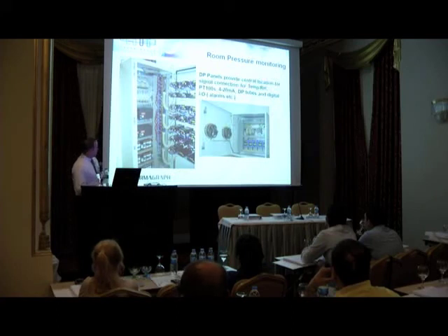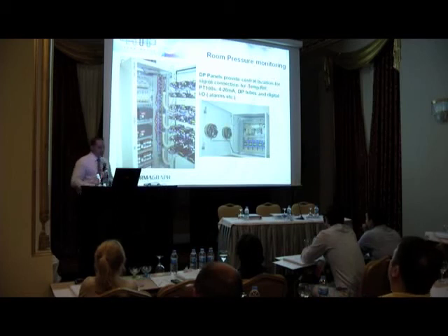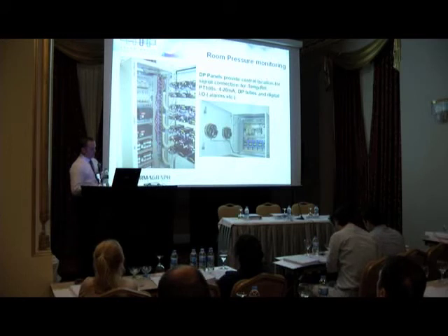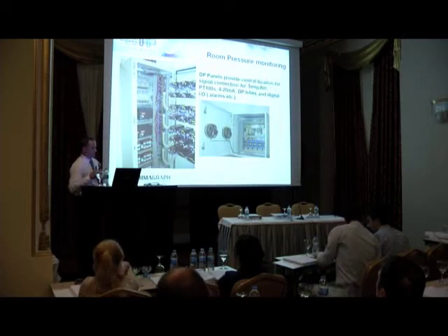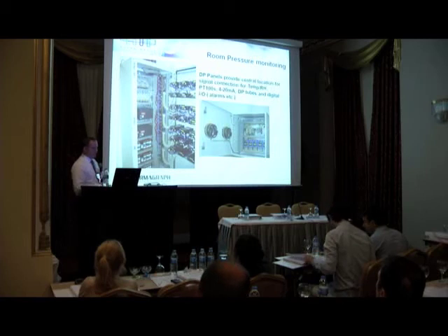We've also mentioned we can do a lot of pressure monitoring. If you're going to go to the expense of putting particle monitoring into an isolator, it's quite an expensive cost. In relation, room pressure monitoring or isolator pressure monitoring is fairly inexpensive. So since you've got the expense of bringing a system in, rather than rely on your magnehelic gauges, which are fine, they only tell you the pressure when you're actually looking at them. If you monitor them, it can cause more problems, but they monitor the pressure in time.